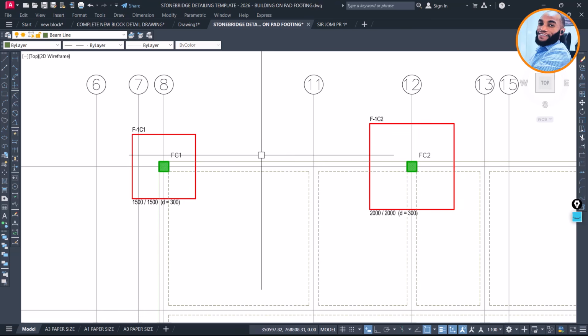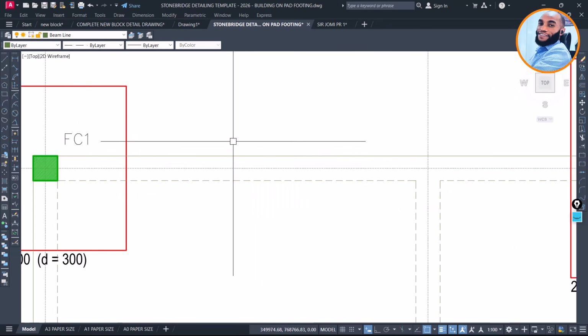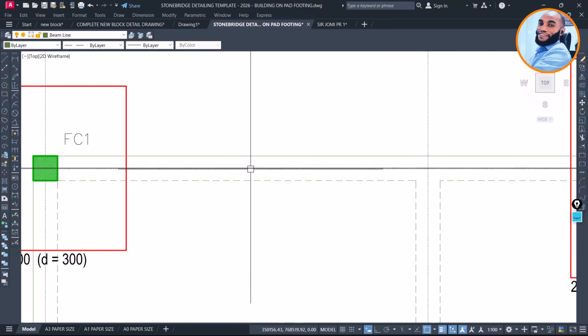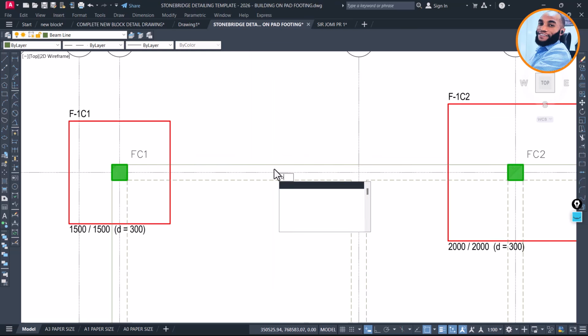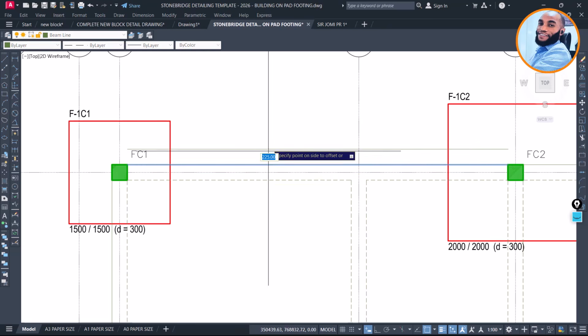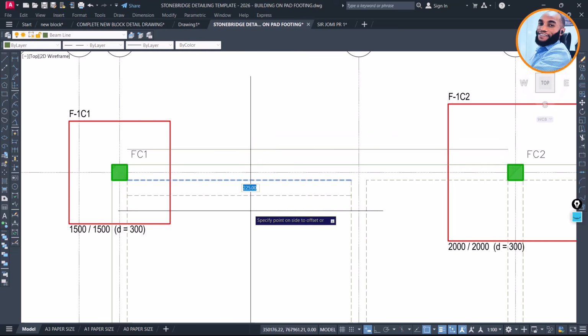And what is the trenches? Trenches is 3 times the block wall thickness. In this case, the block wall thickness is 225, that's 9 inches. So 3 times of it will be what? You just say 225 now. You press offset first, enter, 225, enter, and then enter. So you offset this here, and then you offset that upward and this also downward here.